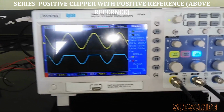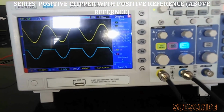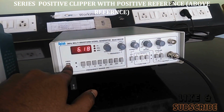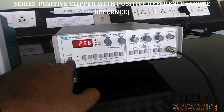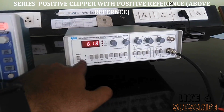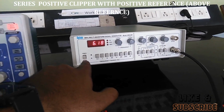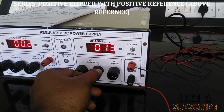I already got the input and output waveform, and I'm going to let you know how to check the output. And this is nothing but a signal generator. Here we need to set the frequency. I already set the frequency to 1 kilohertz and voltage 6 volts peak to peak, or as per the question we can set 10 volts peak to peak, 9 volts peak to peak, whatever the value. Okay, here also I need to set 1.3 as per the calculation.